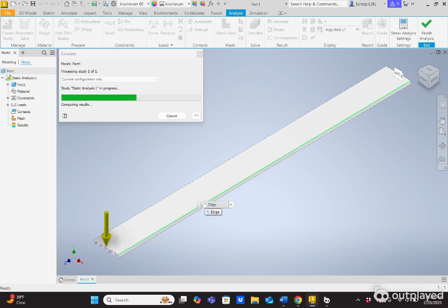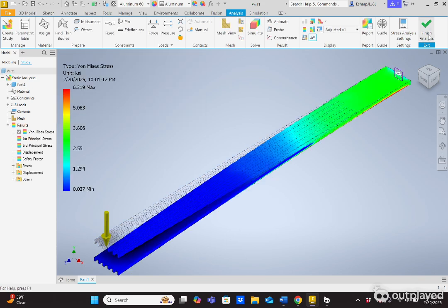So while we're waiting, let's talk about a few of the tips and tricks that you guys can do, right? So you're going to be redesigning this cross-sectional area for each different material that you use. So one thing that I found that was really useful for this project, instead of redoing that calculation over and over, you can put it into Excel one time and create a bunch of different columns for the different materials and then different physical properties of this cross-sectional area. So maybe it's a different number of ridges or depth of ridges or area, etc. that's going to give you that same exact flexural rigidity.